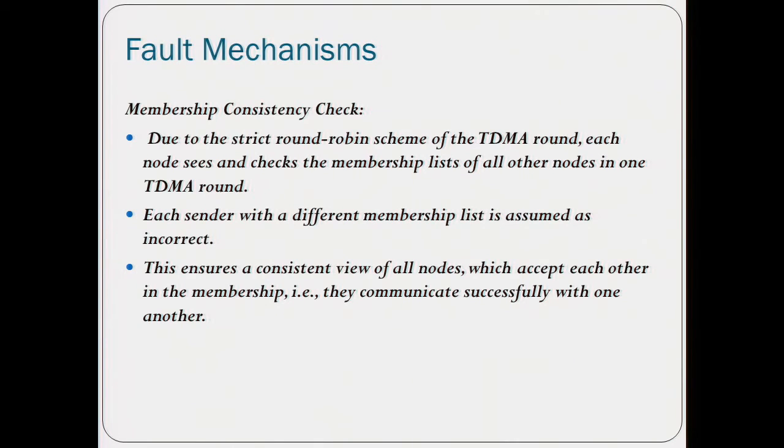And why is it robust that way? Because at the moment in which I realize that this node has gone wrong, I'm going to act. The protocol of TTP is rather complicated because it will allow him to be silent for one cycle. If the next cycle is also silent, then you know it is broken, and so you cut it off. Because it may be partially absent because something has temporarily happened.